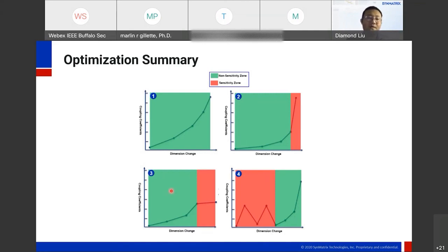And also for these ones, from what we saw during the simulation, it is because the layout of the two cavities is really far apart. When you sweep the arrays or do the tuning screw insertion, it won't reach such couplings. And for the last ones, it may be simulation errors or matrix extraction errors that cause this vibrating result. So you need to check them and find out the root cause and then proceed with the optimizations. Otherwise, it just wastes your time.